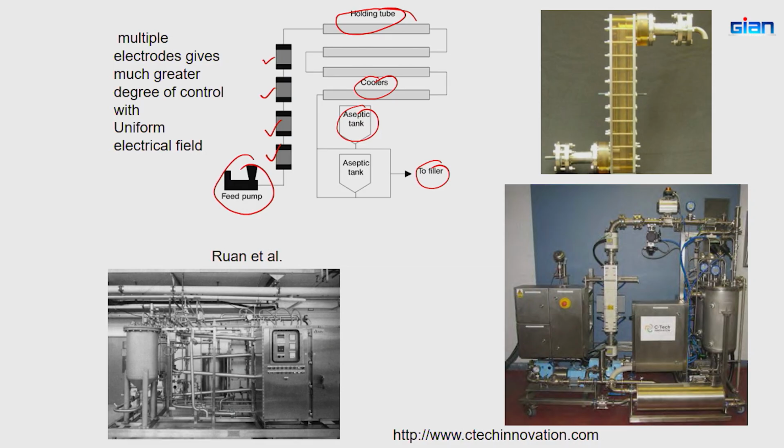So, you go to this stage 3, and then you are going to increase the temperature further. At that higher temperature, say 75 Celsius, the electrical conductivity becomes higher. So, the electrical conductivity value and the temperature are coupled with each other. As the temperature increases the electrical conductivity value, it passes more current, which increases the temperature further, and so on. This is the reason why they have a controlled temperature increase. They probably have 4 heaters so that they can modulate the temperature increase in a controlled manner.